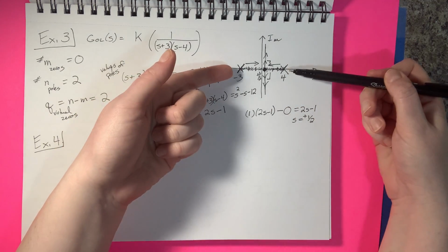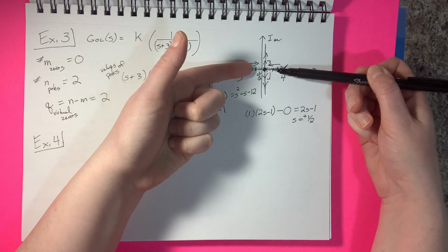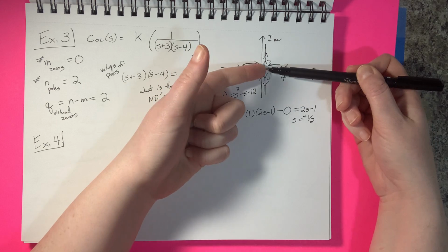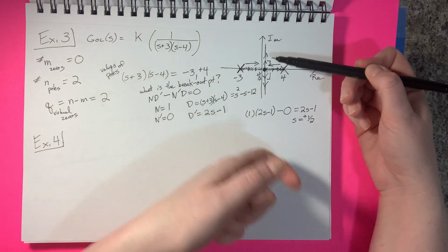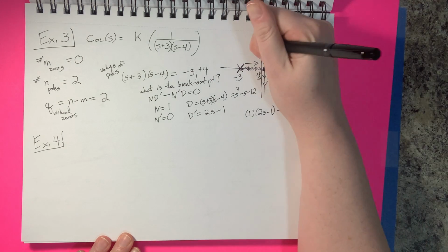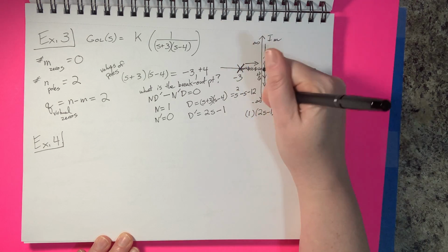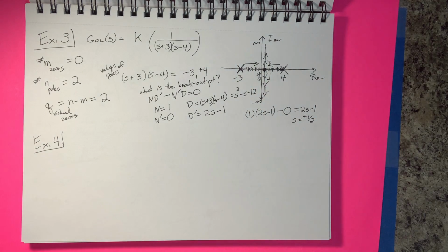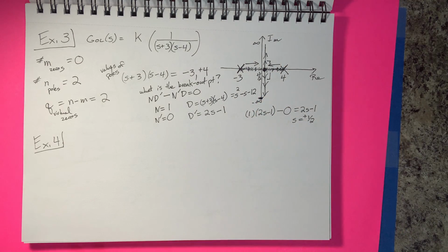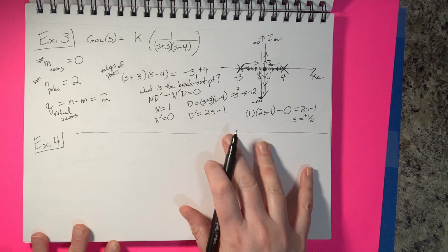So we can see what happens is these poles move along the real axis towards each other, and at 1/2 they collide and they ricochet off at plus and minus 90 degrees out towards the infinite circle, okay? So out here and out here. And actually I don't want to put an arrow on the negative side, but yeah. Okay, so that's our completed locus for example number 3.